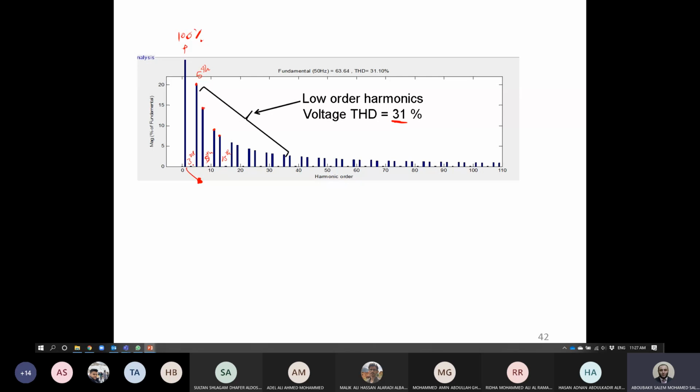And we will discuss in detail, Shabab, third harmonic in three-phase systems after discussing the inverter here. So this is one of the advantages of square wave operation using 180 conduction. The third harmonic and multiples all of time will be 0. We have also another note, Shabab, we don't have any even harmonics.